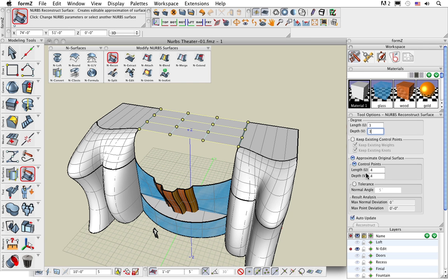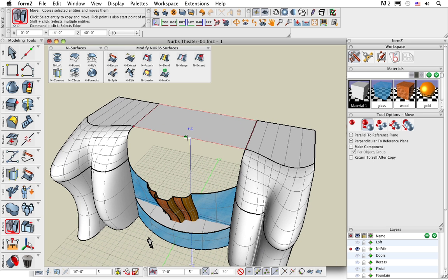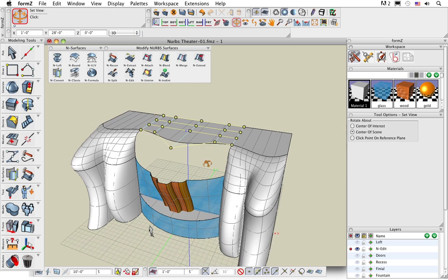And here's another little tip for you. If you use an odd number for the number of control points, in most cases you'll get a control line right in the center of that surface. So for example, with a 4x4, you can see if I change that to 5 control lines, that 5th one, or that odd numbered one, is usually placed somewhere in the center of that surface. So now I can take that one control that's in the center there and maintain some symmetry with that shape. So let's drag that out a certain distance and put a little curvature for that floor in the second story.